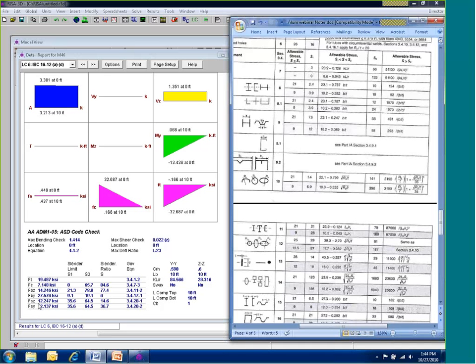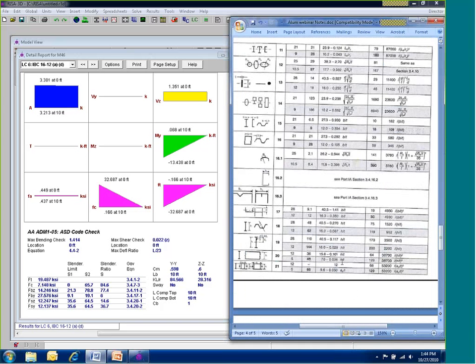Now F shear, we're going to 3.4.20, which is at the very bottom of this list. And that one is using H over T. Okay, so you get a different H with the different directions that you're looking at your shear, if it's in the Z direction or the Y direction, so your H over T value. And where I'm pulling that out is right here, H over T. That's what we're pulling right out of that, and that's what we're displaying right here. Okay, so 14.6 is way below that, and so we're using the 12 number there, you see right there. Again, the same thing happens in the Y direction. It's way below that, or slightly there, and you get that number. Actually, it's going to be right in the middle, sorry, living right in there.